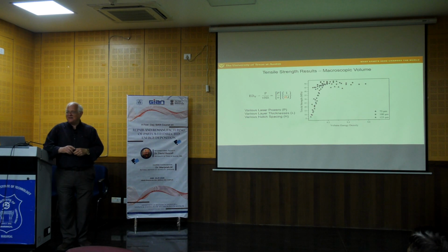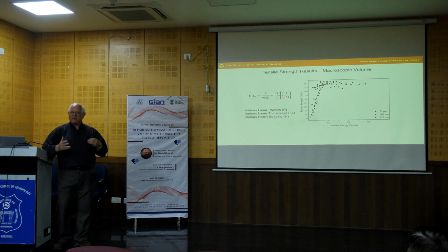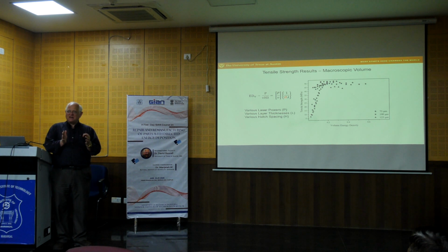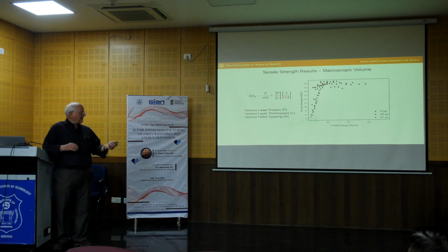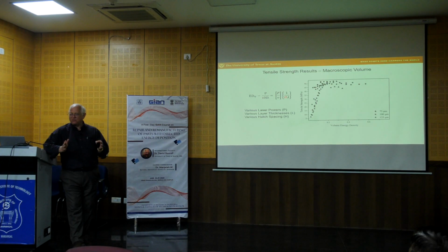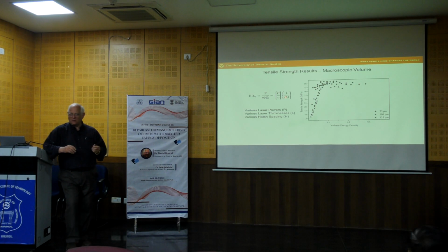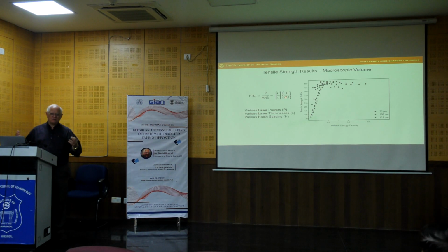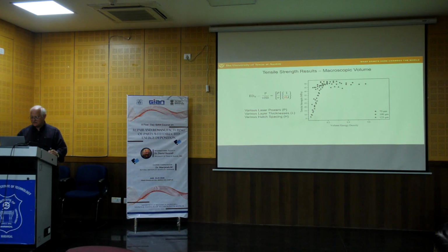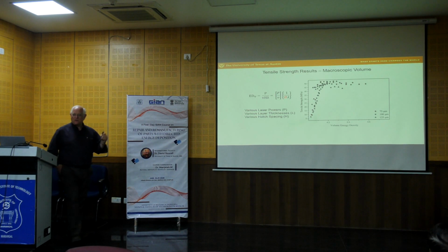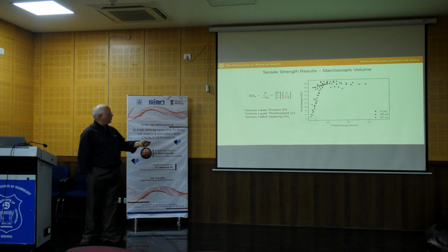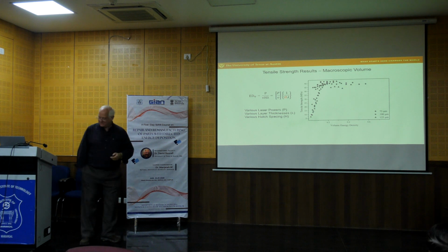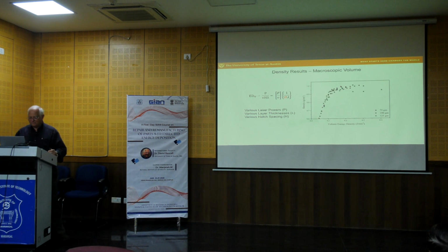the energy density. So again, we can infer from this that there's a range of energy density where I'm at full strength but not full density, because I have to go to about 0.3 joules per cubic millimeter to get fully dense parts, but I get the full strength at a lower value, around 0.15 to 0.2. And so this shows the value of having the energy density plot. I didn't show the other plots for the other four, but basically the results are not as good. And that's the bottom line for that.